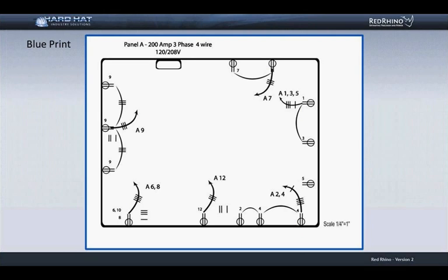I won't show you the takeoff sheet at this time because I'm sure you get it from previous examples. Once all the half-inch EMT is completed, I move on to 3/4 runs, and I take off circuits 1, 3, and 5 next. I will not demonstrate how to roll it off because I think you have enough examples of rolling off EMT conduit. I make the entry on the takeoff sheet for 130 feet of 3/4 inch EMT with 5 number 12s.